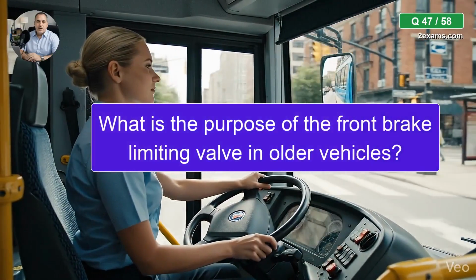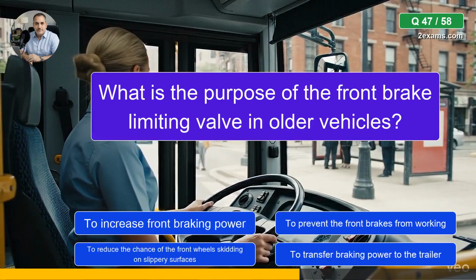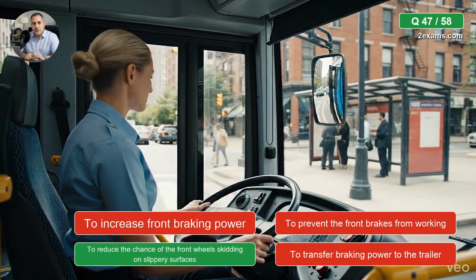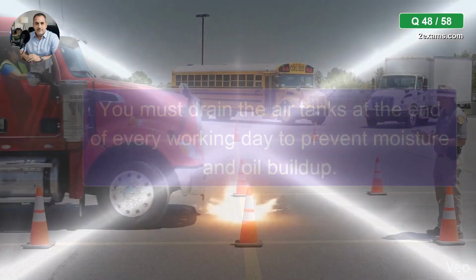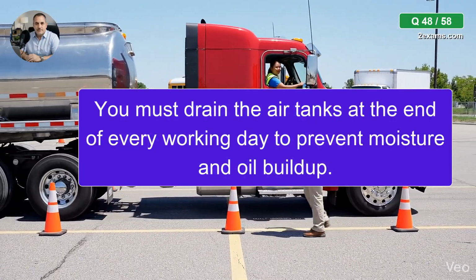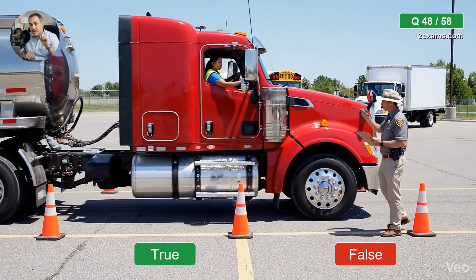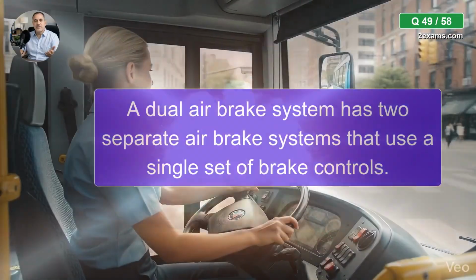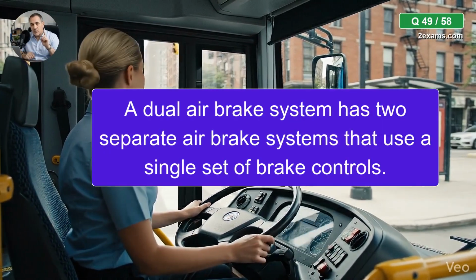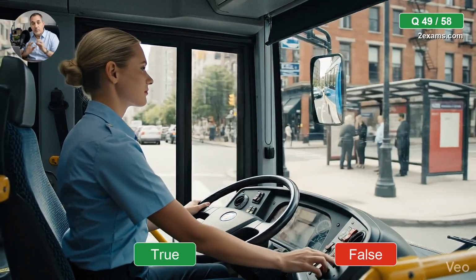What is the purpose of the front brake limiting valve in older vehicles? The correct answer is, to reduce the chance of the front wheels skidding on slippery surfaces. You must drain the air tanks at the end of every working day to prevent moisture and oil buildup. The correct answer is, true. A dual air brake system has two separate air brake systems that use a single set of brake controls. The correct answer is, true.